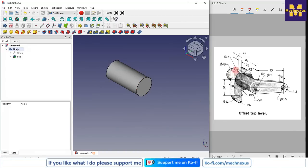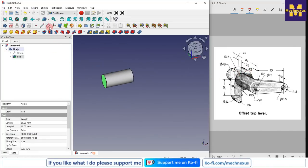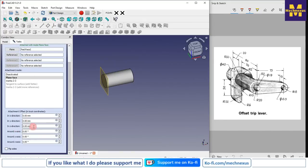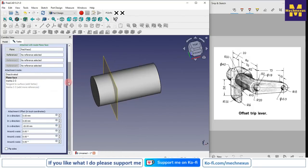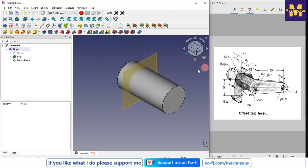Now to create this face or this solid, we require a datum plane. So we will select this back face and click on the datum, and in the Z direction I will give the 20 mm distance. So you can see that the datum plane has been created at a distance of 20 mm. Now click on OK. Now click on the rebuild symbol, switch to the isometric.